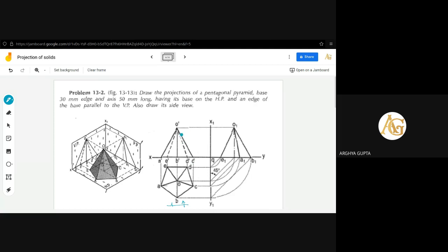Now the side view. Okay, so draw the side view. Again, you have to take the projection lines from all the points. So E and D will coincide. Projection from A and C will coincide. Okay, if you draw a horizontal line, then you'll find that A and C will coincide. Then projection from B. Now 1, 2, 3, 4. So 4 lines have been obtained.